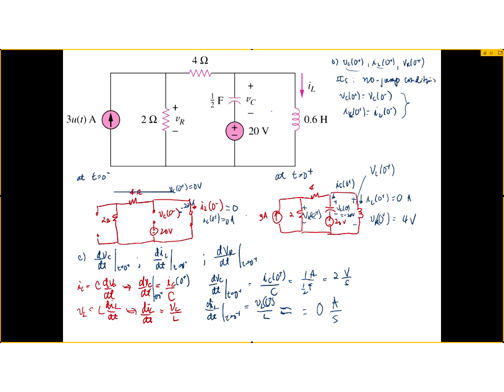Are these two okay? As I mentioned, the first two are really not that bad because the derivatives we're looking for pertain to variables that we've already seen before. We've seen dVc/dt before in the context of the definition of the current in the capacitor. We have seen dIL/dt before in the context of voltage in the inductor. However, the definition of VR does not involve any kind of derivative. Yes?